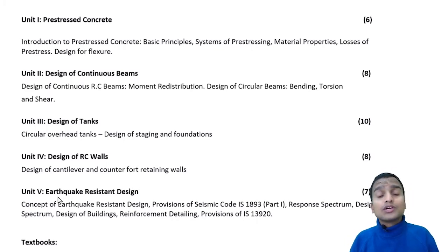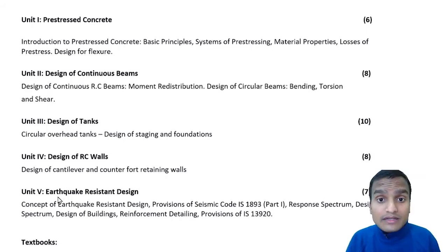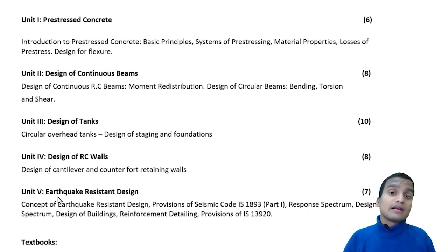Okay, and here we apply the principle of moment redistribution. Three moment theorem, etc. And we will also be trying to understand design of circular beams, and circular beams involve the concept of bending as well as torsion as well as shear. So now you will be using not only shear force diagram and bending moment diagram, you will also be drawing torsional moment diagram.